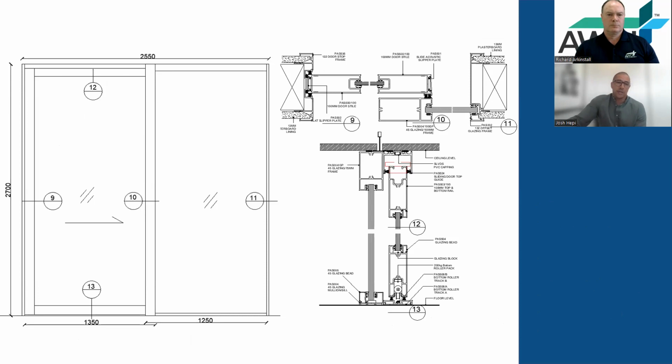And just for the final exercise, I thought I'd take you through this example of a slider. Again, to the ceiling height, 90mm stud. We're going to look at sliding the door within the wall thickness with offsetting the glazing to one side. Let's just say we've extrapolated this out of a set of plans, and this is what we're working with. So again, I'd work out the vertical components, the horizontal, and then the door profiles, and then the accessories. So with that in mind,